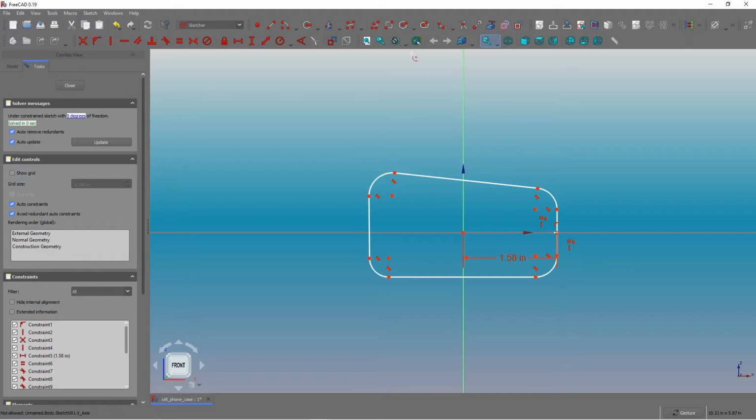I had a horizontal constraint, but it still moved, but I can fix that by putting a horizontal constraint again. So then this gets weird, but let's put some more constraints. Okay, so this one needs a horizontal constraint as well. Okay, so that fixed that problem, but my fillets are kind of all weird.